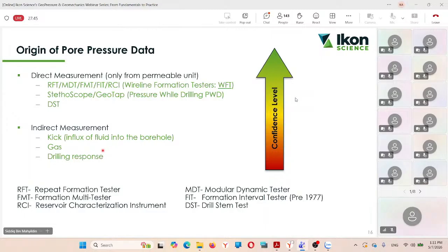For example, you drill a well with a certain mud weight, 8 ppg, 9 ppg. At 9 ppg, pounds per gallon, you see gas or cake. So it suggests that your pore pressure is actually higher than your mud weight, because now you see influx. You do not know what the number is, what the pore pressure is, because this is not a direct measurement, but you know that it could be higher than 9 ppg.